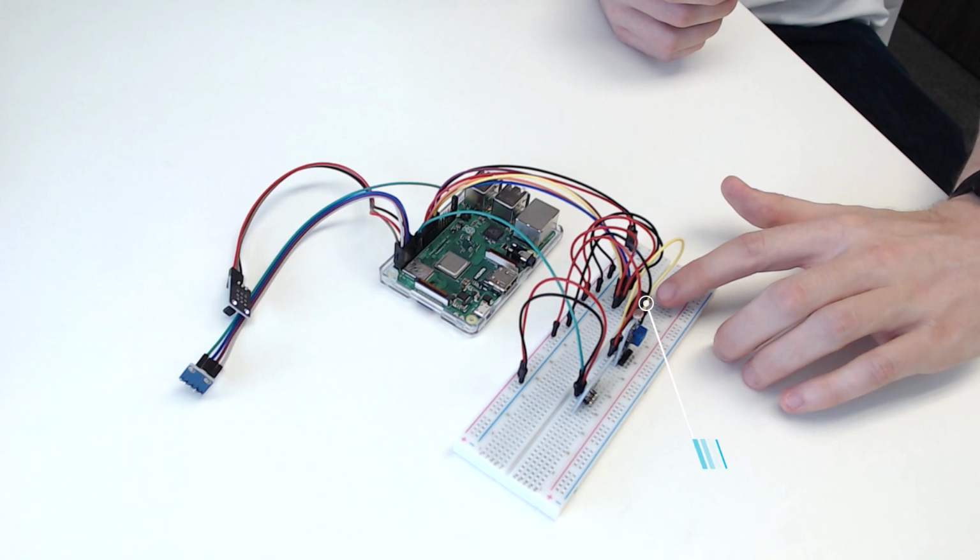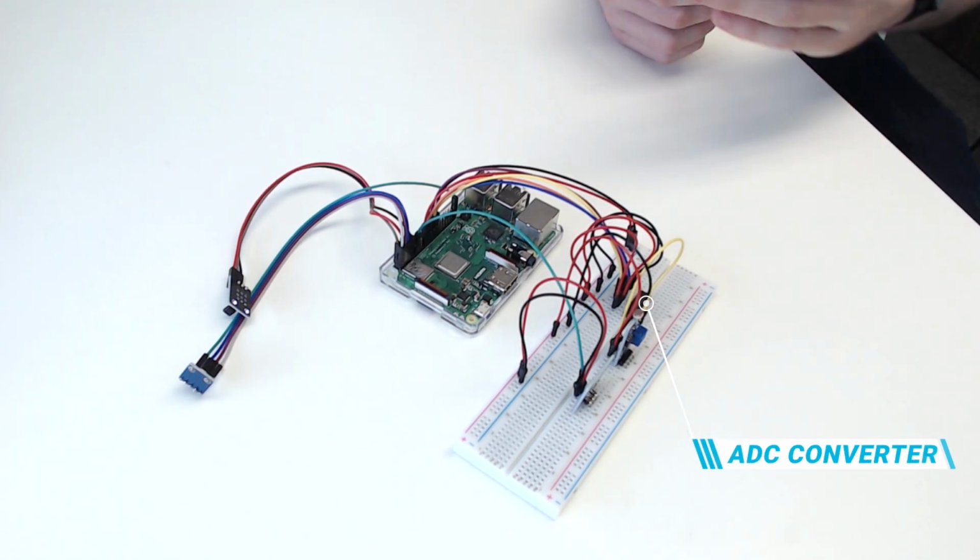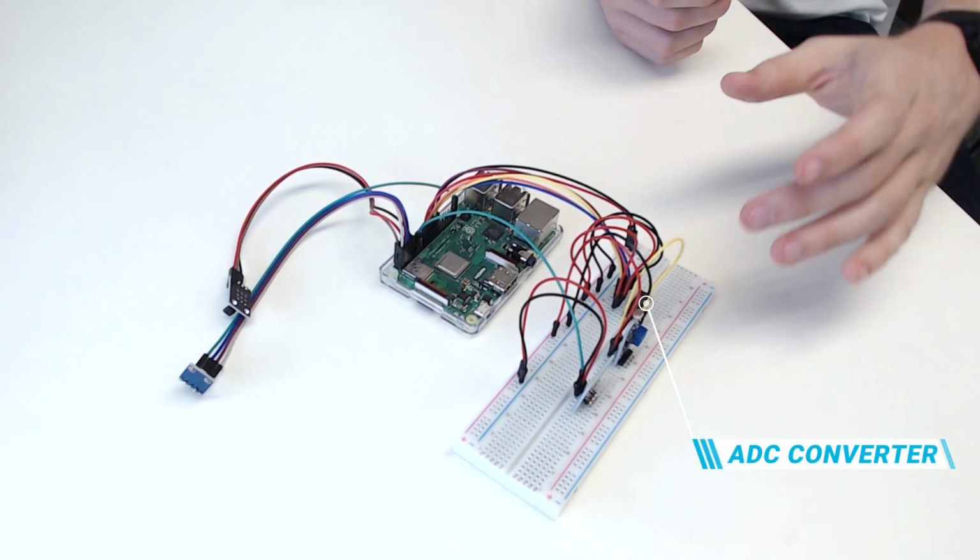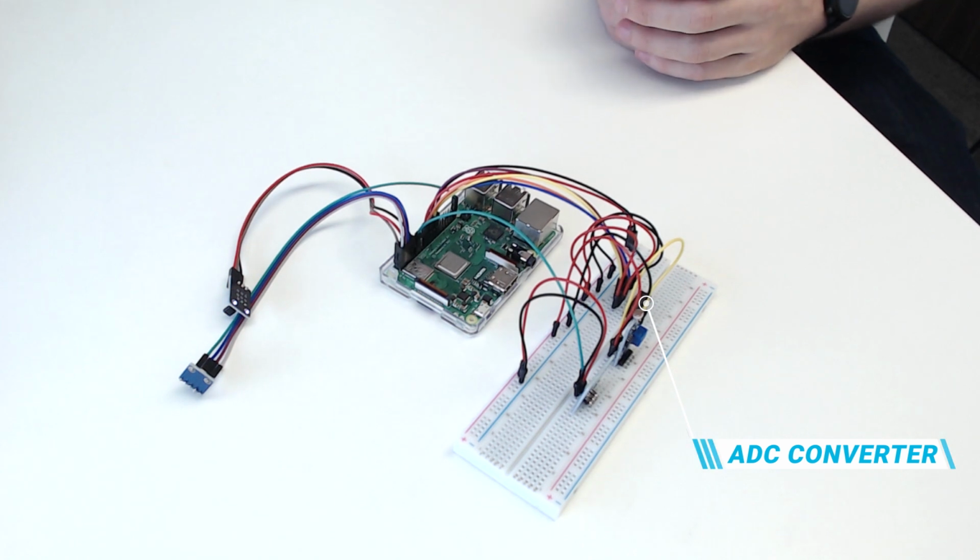That is because it is sending out analog signals. For the Raspberry Pi to be able to use that signal, we have to convert it first to digital. So that's what you see over here. We have a small analog to digital converter that we use to convert that signal and then send it over to the Raspberry Pi. On that Raspberry Pi, this is where the IoT platform software is running, and that will basically just pick up all the sensor data every 30 seconds, and send it over into the cloud from where we can pick it up in TrendMiner for our analytics.